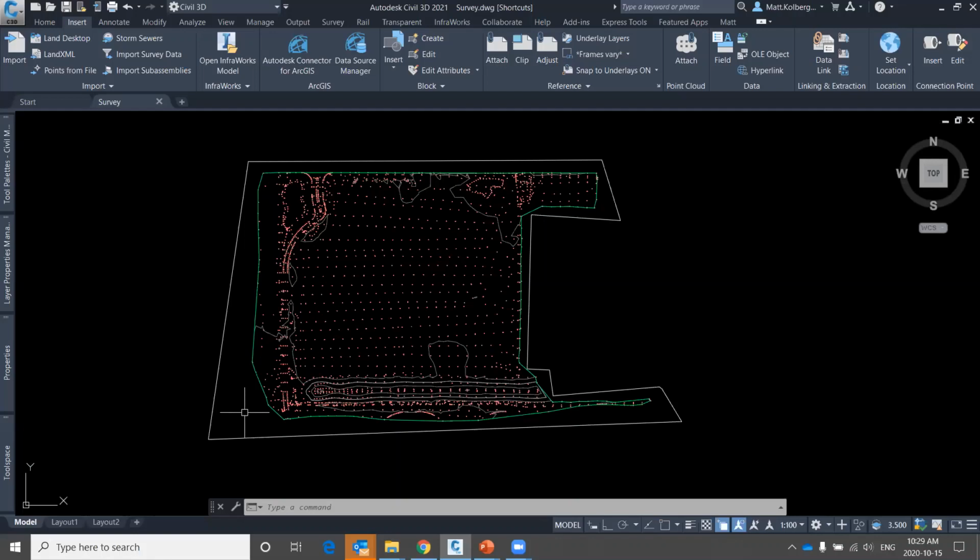A huge advantage to using BIM 360 instead of a VPN is the files are local. They are not on a server. Yes, they are in the cloud, so yes, you do have to download the files once. But once they're on your computer, they're on your computer. And Civil 3D works best when files are stored locally.